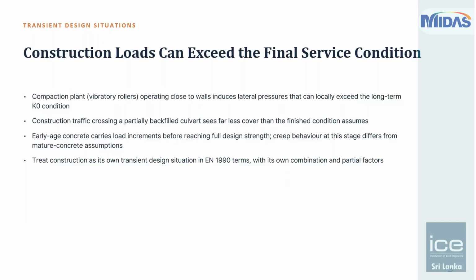One more thing that is important is that during construction, the concrete might not be hardened before 28 days. And if compaction is carried out before those 28 days, then basically you are applying the design loads on the structure before it has achieved its full strength. So the reinforcement that you have provided, assuming that the structure will see such loads when it has gained full strength, will not be enough anymore.